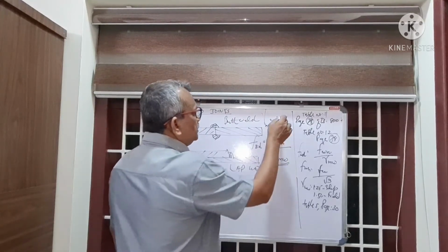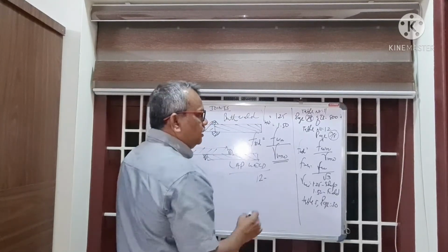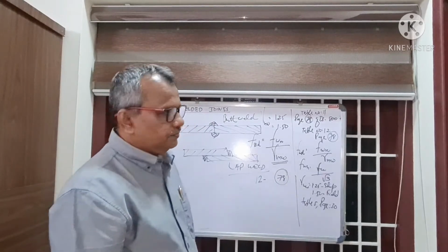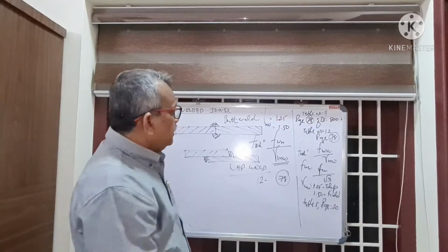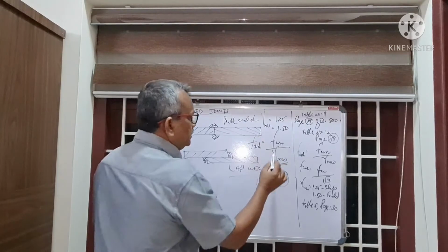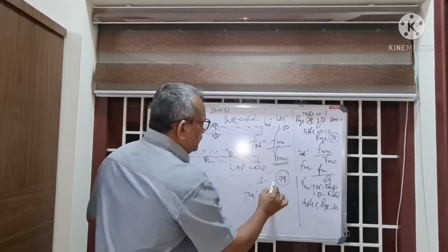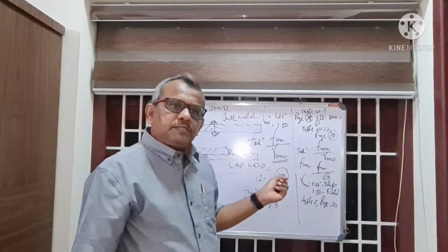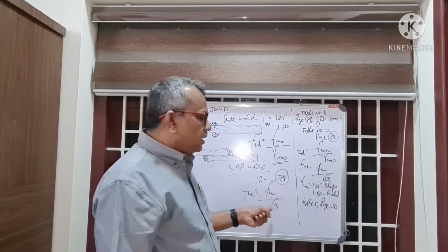This equation and these values are given in Table number 12, page number 78 of IS 800:2007, right? And as in the case of the bolted joint we already studied, the nominal shear FWN can be found out from the formula Fu by root 3. What is Fu? The ultimate tensile strength of the welded joint, divided by root 3.